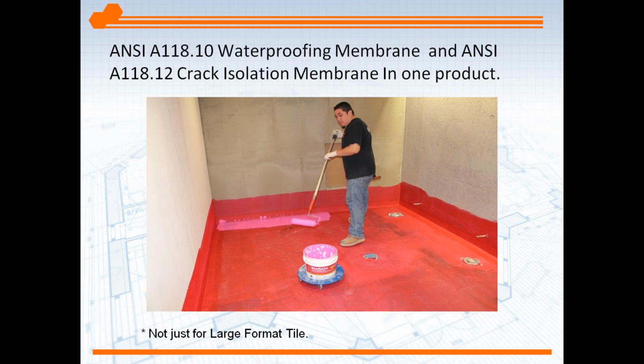There's also waterproofing products that are installed more like a wallpaper. Just think of that concept of wallpaper. So you would put some mortar on the wall, you would apply the waterproof paper to it, and then you would seal the seams and put the next piece on. There's products around the market as well. Just be aware of those as well. So